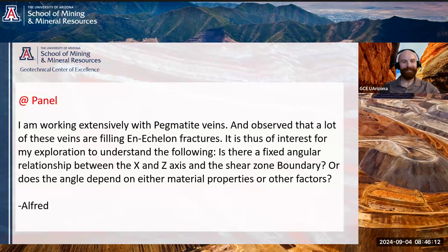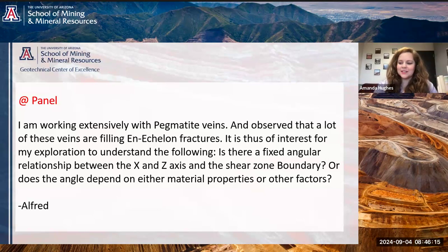Well, so the angular relationship with the boundary of the shear zone, this is hard to draw without sketching, is that en echelon fractures, the overall trend of them is going to be at approximately the Coulomb orientation relative to the overall stress field. Now, if you assumed a linear Coulomb failure criterion, then that would always have the same orientation relative to the maximum compressive stress direction.